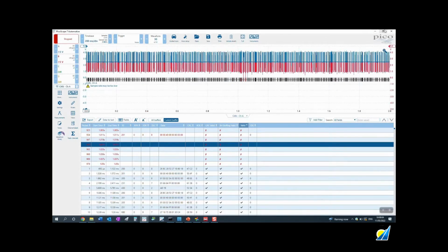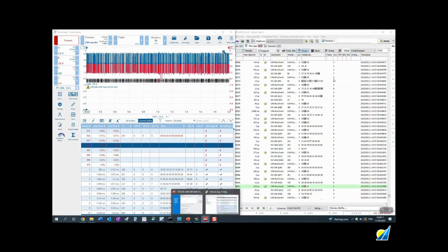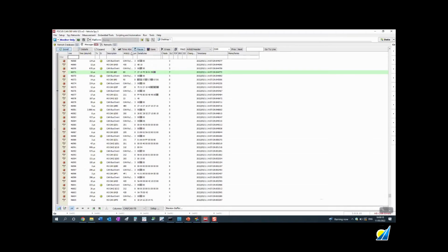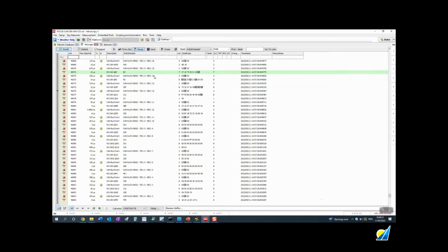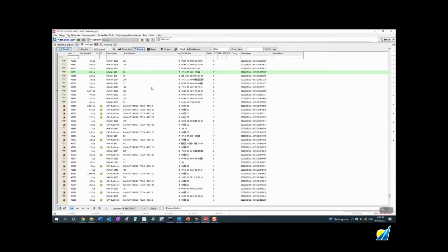So multiple errors there. Let's just go back to Vehicle Spy. And what is Vehicle Spy reporting? Let's go full screen there and have a look at the explanations. So we see something here called REC, that's receive error count. And I'll just scroll up. Alright, so it starts here at final message that came through and decoded accurately was ID 231. Then we start receiving error counts 9, 10, 18, and then they start decreasing. As they decrease, we start to get other messages coming through.